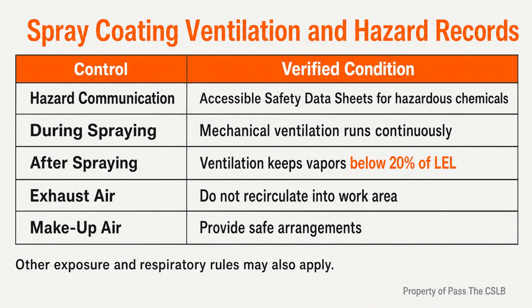For field control, I would use a simple product register before finish work begins. For each covered material, record the manufacturer, exact product, intended use, applicable category, regulatory value or other governing measure, supporting manufacturer document, and approval status. This is a management method, not a claim that California requires one particular binder format.